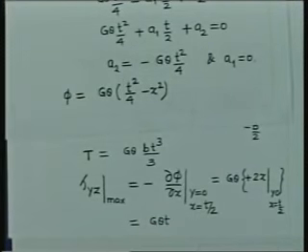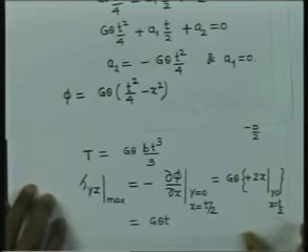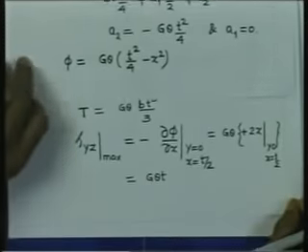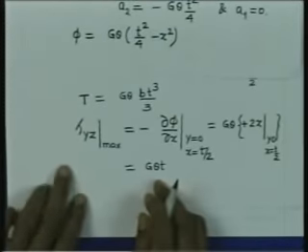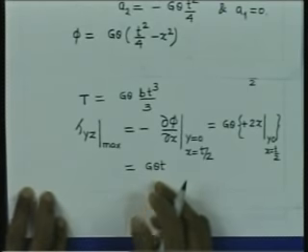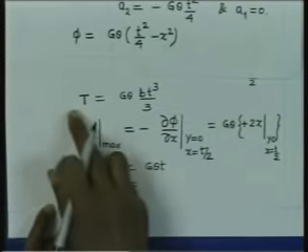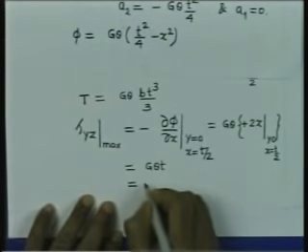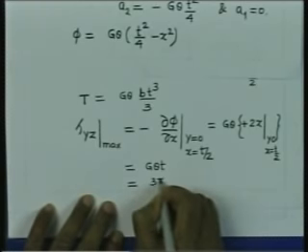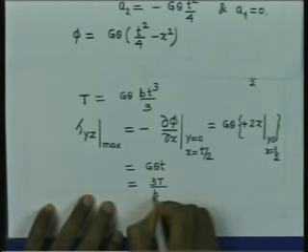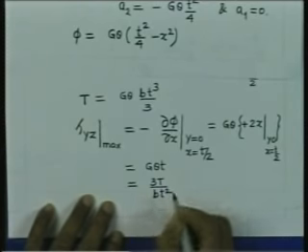So, the maximum shear stress is this much, and since we have g theta available in terms of torque, if we substitute the value of g theta equal to 3T by b t cube, then it gives us 3T by b t square. So, that is the maximum stress.